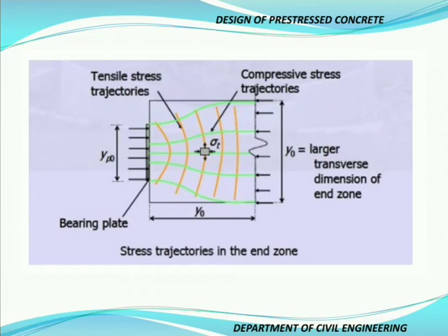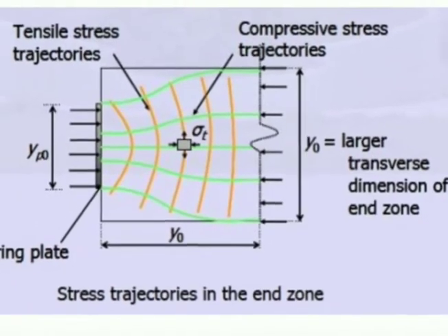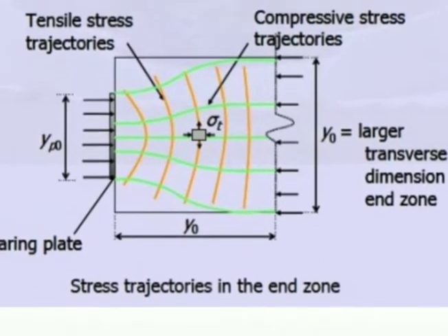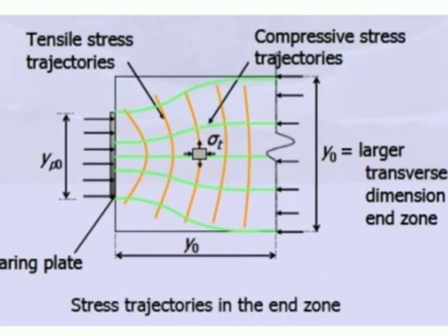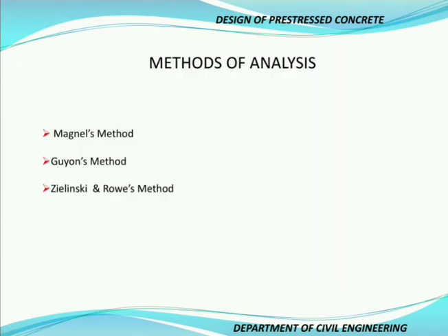So this view tells us the importance of your anchorage zone, as we have both tensile as well as compressive stresses acting in this region at a time. Hence, a proper reinforcement needs to be designed for this section.